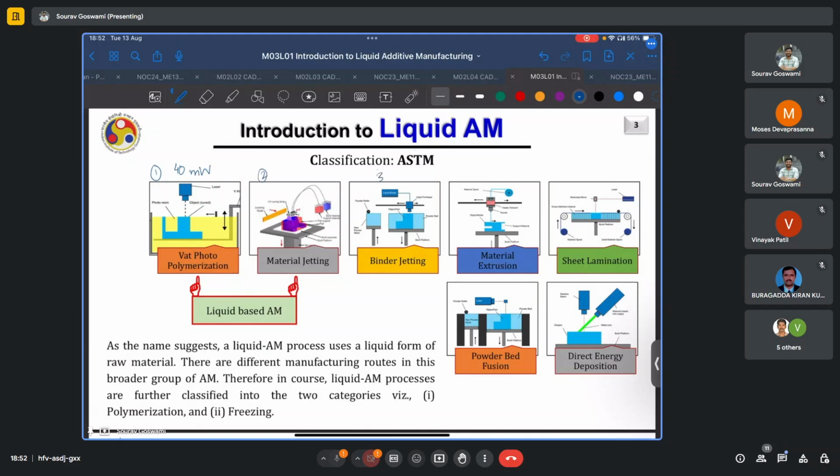2, 3, 4, powder bed fusion typically utilizes, say, a laser of the order of 500 watts. For DED, you can have anywhere between 3 to 8 kilowatts. At IIT Bombay, in our lab, we have a 5-axis hybrid additive manufacturing machine, which is a laser wire DED machine, equipped with a 3 kilowatt laser head. We are looking to augment it even further.